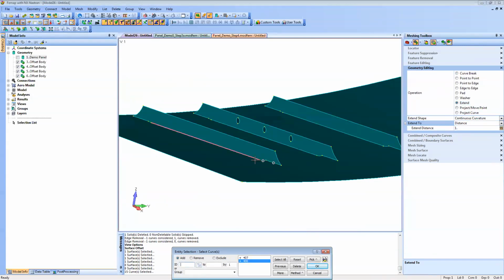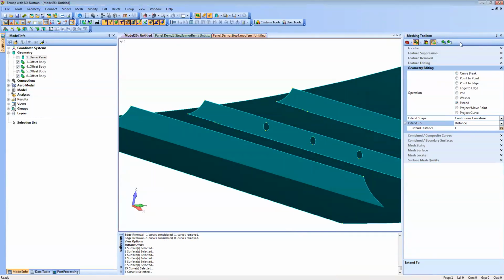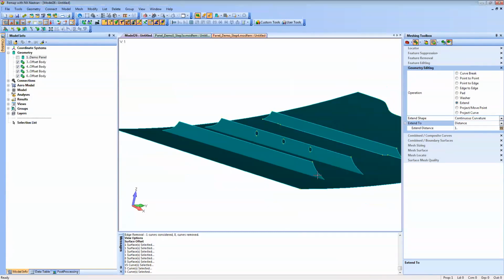And then the one thing to note here is that this is Femap version 11.4.2 I'm using, so we have that add tangent surfaces I showed you a couple minutes ago, but unfortunately there's no add tangent curves yet, but I believe Femap 12 will have that feature, so stay tuned for that, and hopefully this will be a little bit quicker and easier in Femap 12. So, okay, and then we can do that for the other 3 grids, so click all those edges. Okay.